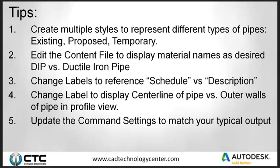My opinion, again, it's just my opinion, but just showing center line of pipe looks a lot better than showing outside of pipe and then end of pipes, especially when you use that top surface or follow surface tool. You don't want to see every 20 feet. You don't want to see that vertical line in there.